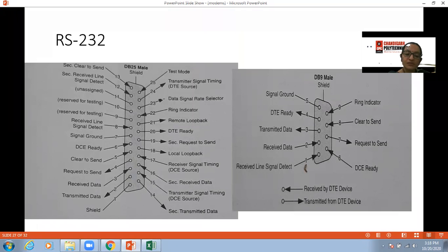And as specified in the standards, RS-232 is officially considered to be suitable only for data rates up to 20 kbps, which will come in your exams for a one mark question: what is the data rate of RS-232 connector? That it is 20 kbps and its distance is up to 50 feet. The RS-232 is often run at 1200 and 2400 bps for the distance up to 20 feet, and at 9600 bps for a distance of as much as 500 feet.